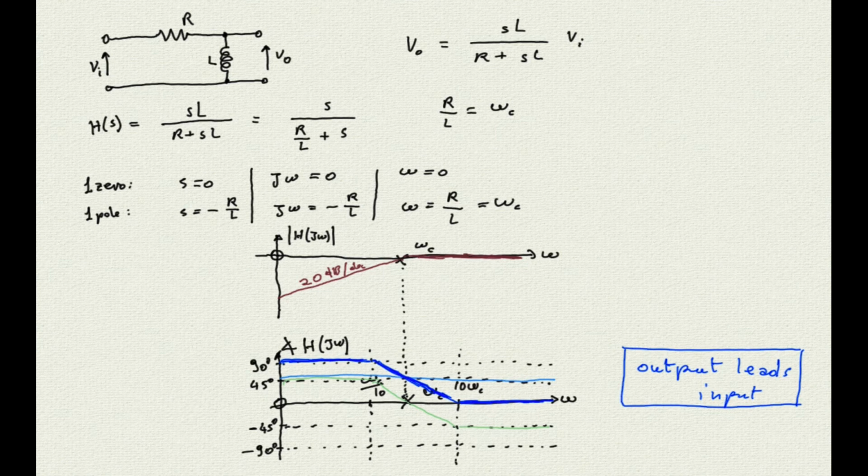Notice how these diagrams are basically identical to the ones for the RC circuit. The only difference is the way the cutoff frequency has been calculated, since the components are different, but the kind of circuit is the same, another passive first-order high-pass filter. Let's now run the same measurements as for the first circuit, so we can verify that the theory works as well for inductors and capacitors.